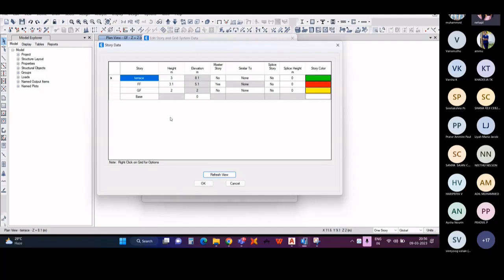After that, we can enter the details of our architectural plan. So we can enter the height. Corresponding to ground level, we will be entering the height of the foundation. So say if you are providing footing for this particular residential building, normally we will be providing a height of 2 meter. So say if we are providing pile foundation to this particular building, for pile foundation, the height from base to ground floor will be normally 10 times the diameter of pile or 5 meter. So consider we are providing footing here, so we'll be providing the value 2 here.